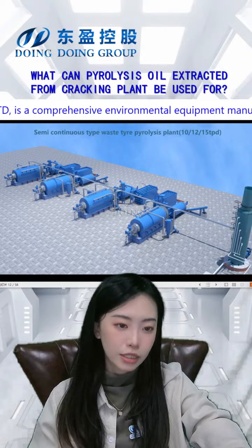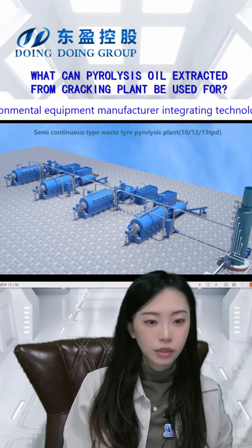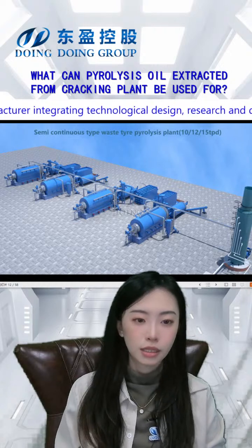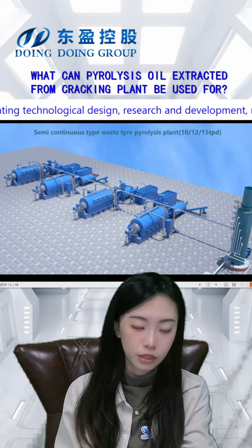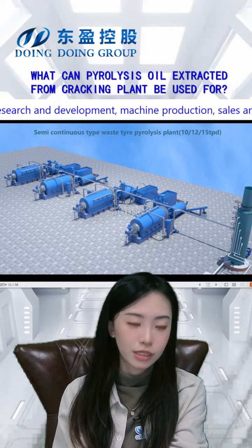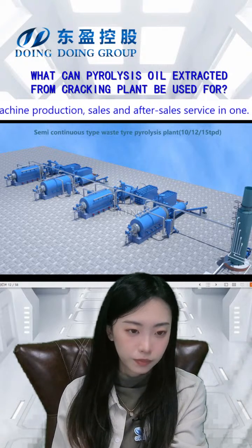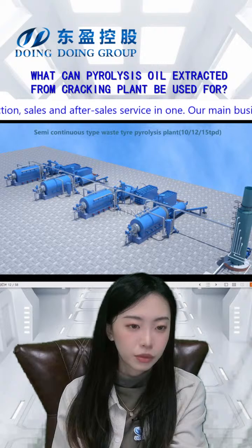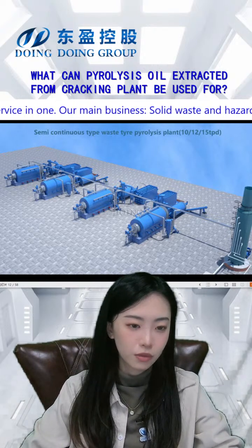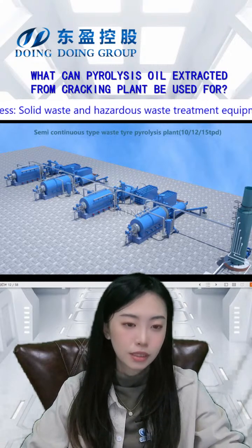We need to crush the waste tire into rubber powder, and the waste plastic we need to change into plastic particles. This is some limitation of the raw materials, and some materials are not suitable for the semi-continuous one, like aluminium ingot, oil sludge, solid or semi-solid state oil sludge, or other kinds of materials that are not easy to crush or scratch.